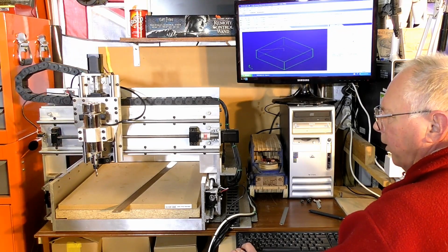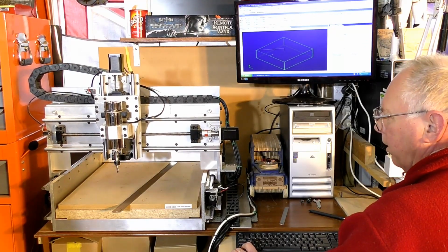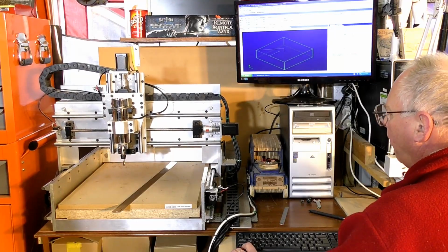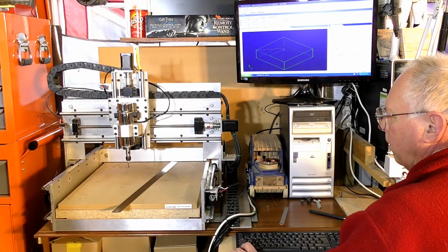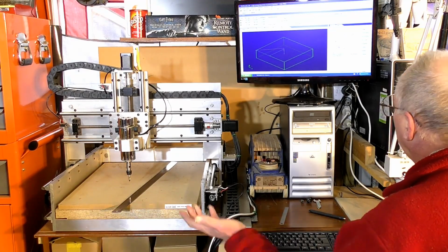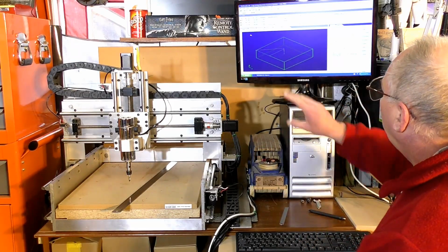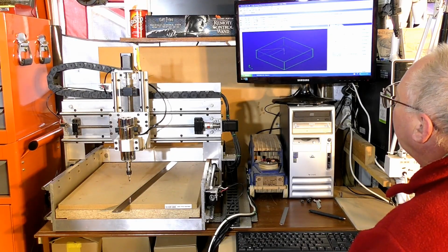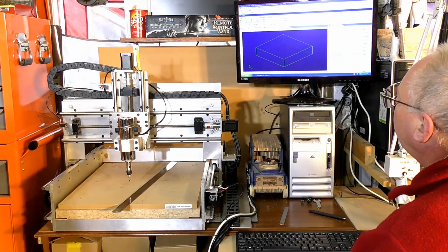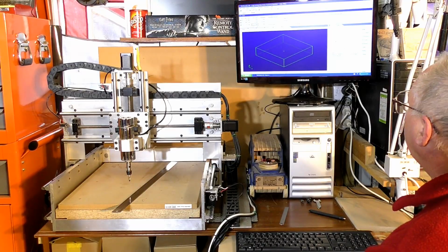Okay, so we're just going to fetch it over here a bit, and then back a little, and then down, and we'll just set an imaginary G54 or work offset there, and really you just hover over each individual box here. This is the X, press for 0, Y, press for 0, and Z, and that is now the work offset set.